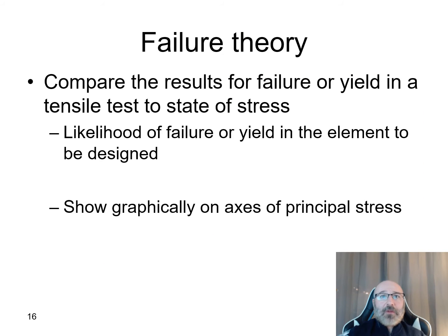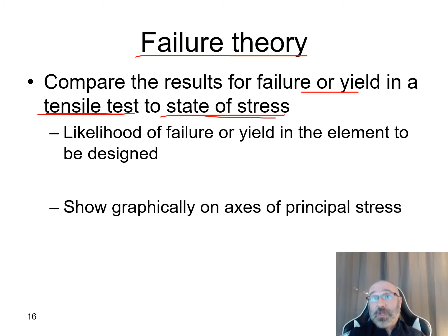So continuing on with our failure theory here, if we want to predict failure, if it's going to occur, one thing that we can do is compare the results for failure or yield in a tensile test to the state of stress right there. That's why it's important to take these tensile tests and compare that to the state of stress. From that, we can determine the likelihood of failure or yield in the element to be designed. We could actually do this in developing our prototypes as we're making these samples: test and compare from the tensile test and go ahead with our design process from there to tweak it to meet the correct specifications.